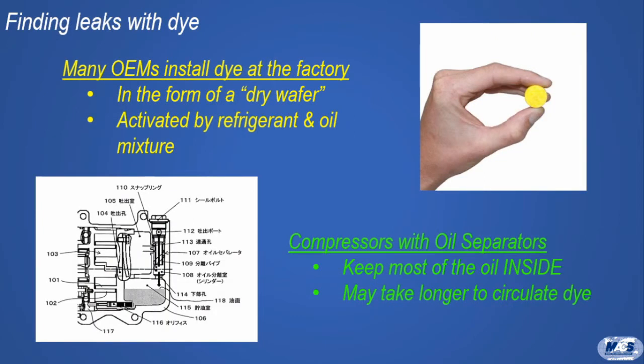The fact is that some leaks, certainly at shaft seals, also at some joints, only show up when the system is running. But you can't probe the system with an electronic leak detector when the system is running. That means there are leaks you'll only find if you run a system with trace dye in it. One reason why many industry engineers continue to put trace dye pellets into the system on the assembly line. They have plenty of empirical evidence that it works.